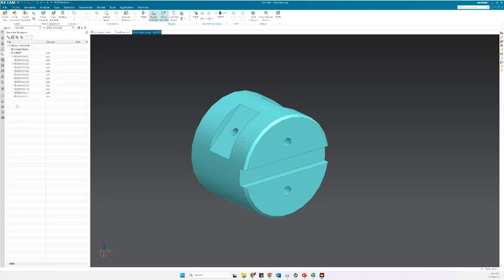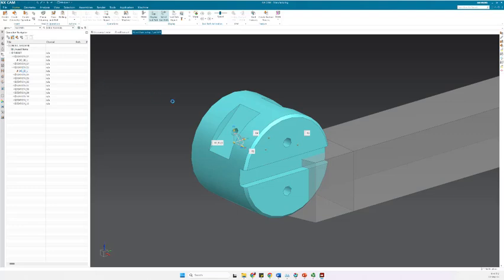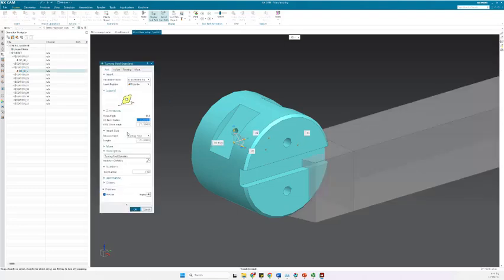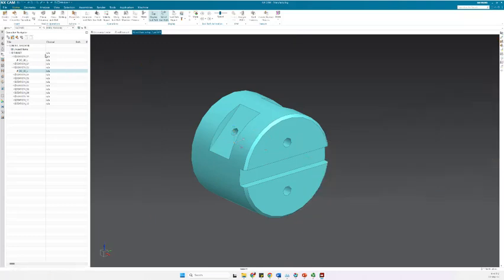Now I have the turrets open. I have two predefined tools, both outside diameter cutting, and by double clicking those, I would be able to change the parameters here and even the holder and shanks and holders and so on. In another tab, I have the geometry view, which by clicking on this positive sign, I have now open.